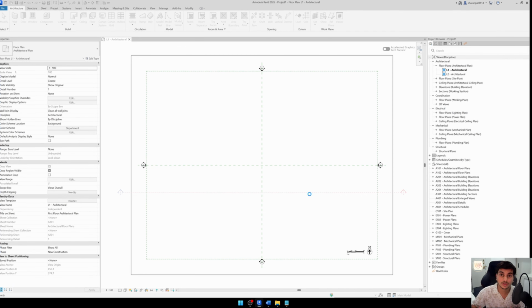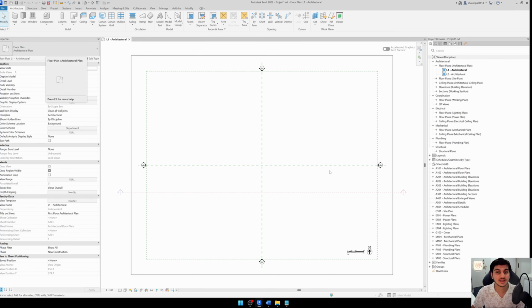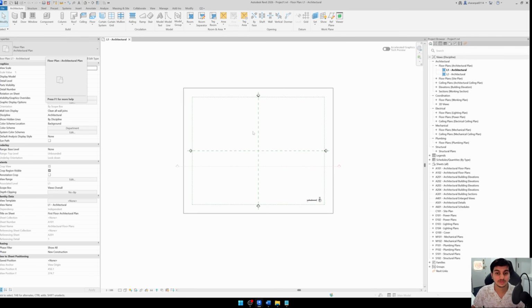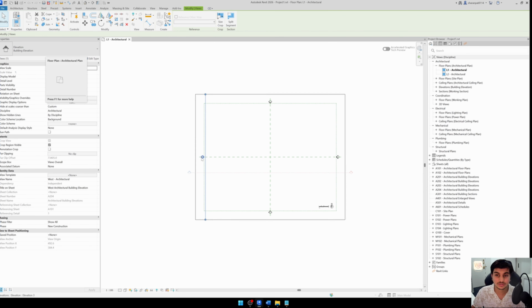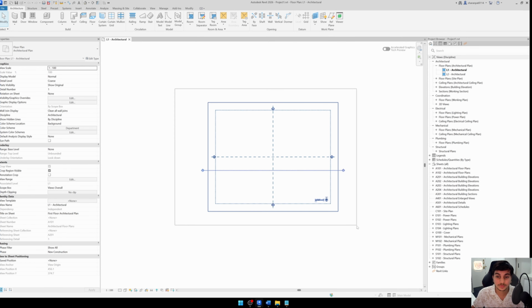Whenever you save, your last 2 backups will also be saved with the extension dot 001, dot 002. You can check it. Okay, let's start. So this is your workspace which I told you about yesterday, and this is your elevations. Yesterday we learned regarding this workspace. Now let's begin with walls, doors and windows.